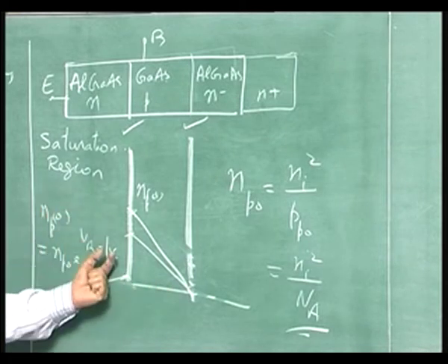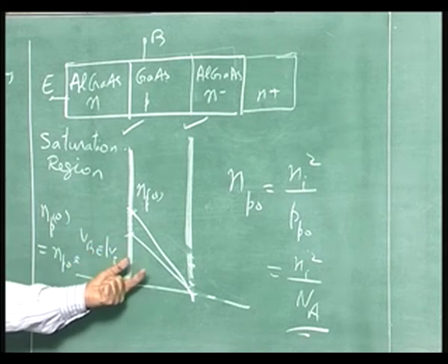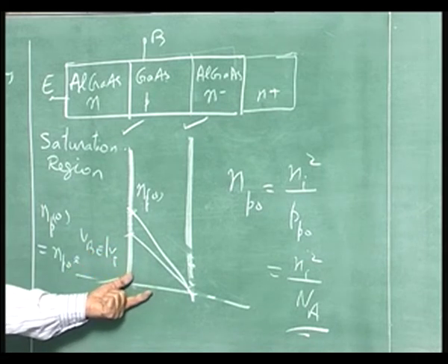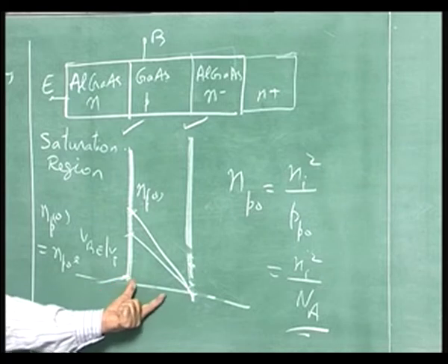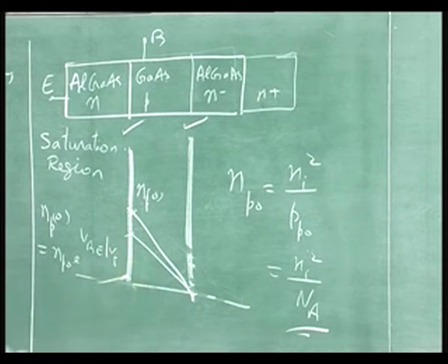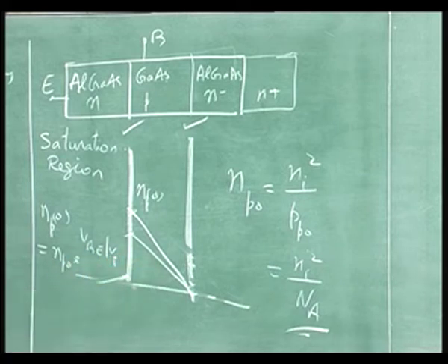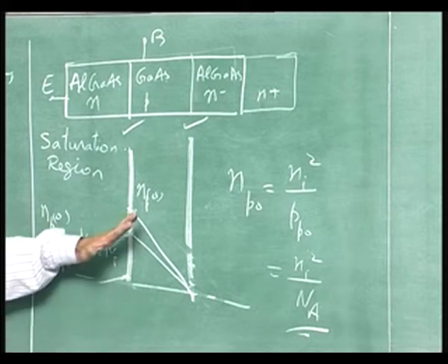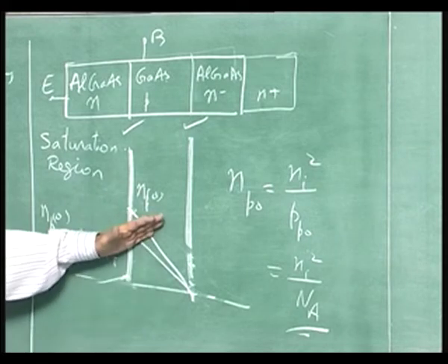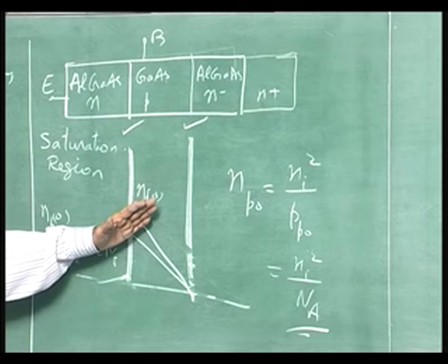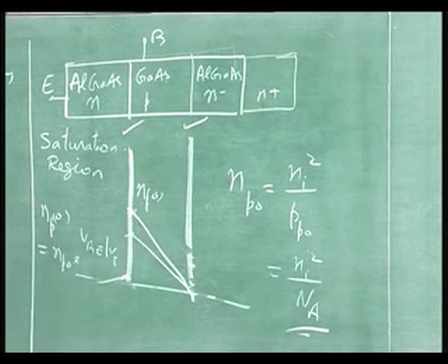You can increase the speed or reduce the transit time not only by reducing W; if I can bring in electric field, the transport will be faster. The velocity by diffusion is smaller compared to velocity by drift. So, if I introduce drift by some means, I am in business. I can increase the speed, transit time can reduce by a factor of 5, 10.